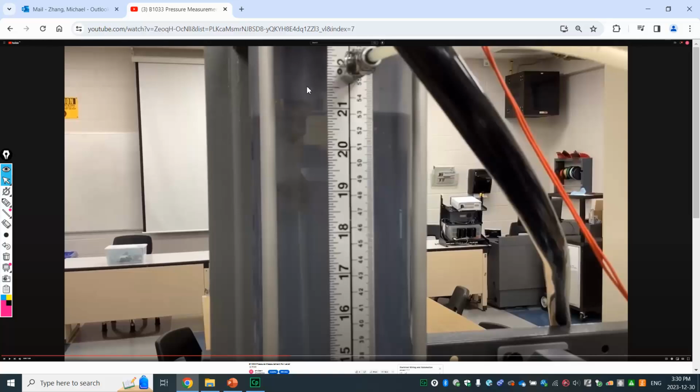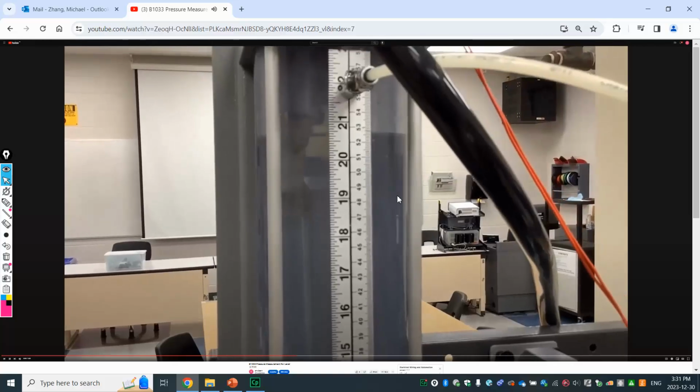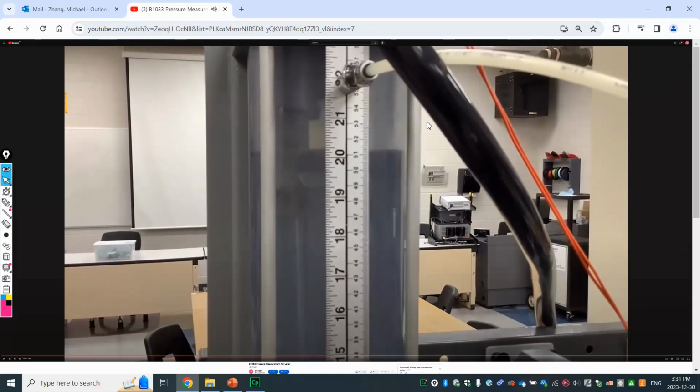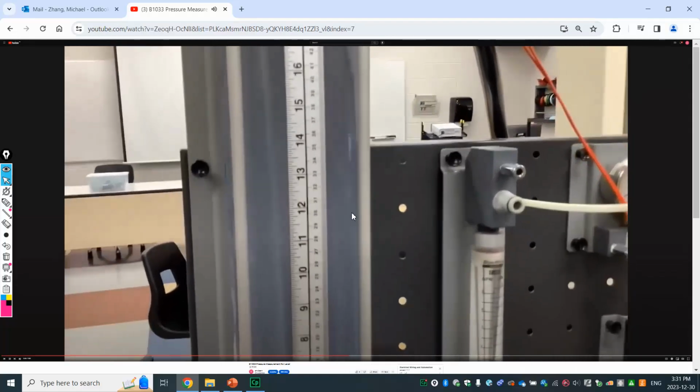You can see here, that's what we talked about, the flow switch. This part is the flow switch. In the lab, you can try to raise the water level to here, and you will see the pump being cut out on the control. That's why the LSH is used to control the high level. These are the two wires. You can see the two wires come out from the top into the control circuit.